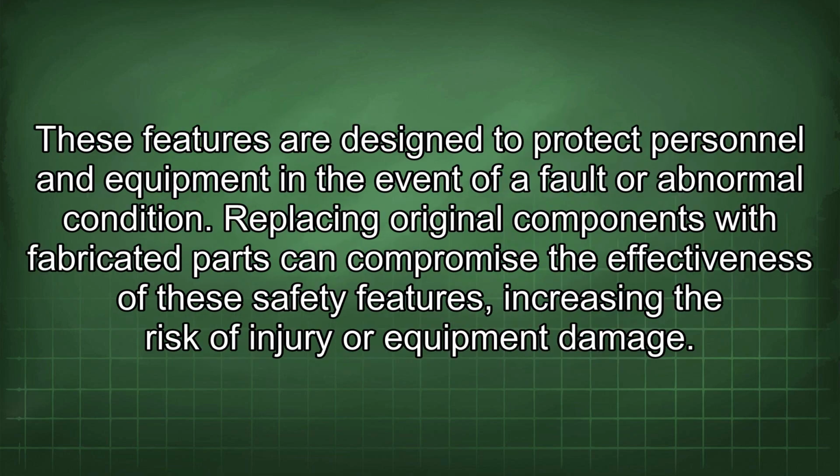The manufacturer's original design also incorporates various safety features such as interlocks, protective relays, and grounding systems. These features are designed to protect personnel and equipment in the event of a fault or abnormal condition. Replacing original components with fabricated parts can compromise the effectiveness of these safety features, increasing the risk of injury or